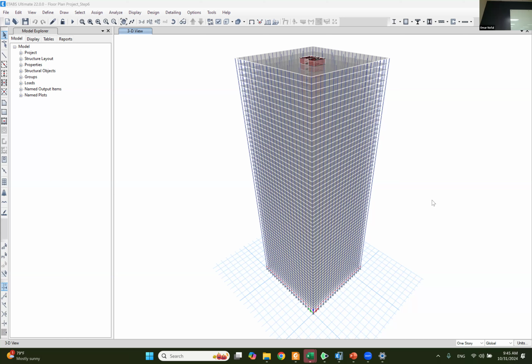Once you know the maximum acceleration, you can multiply by the mass of the building, with some manipulation in the formula, and find out how much force this building is going to have. So the response spectrum basically converted this whole seismic earthquake signal to one single force at the base of the building. That's what we have been talking about for 2 lectures: how we can convert a seismic load from a dynamic load to one base shear at the building.